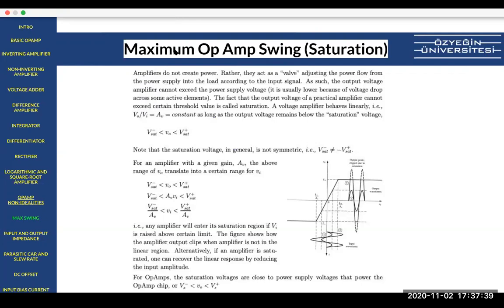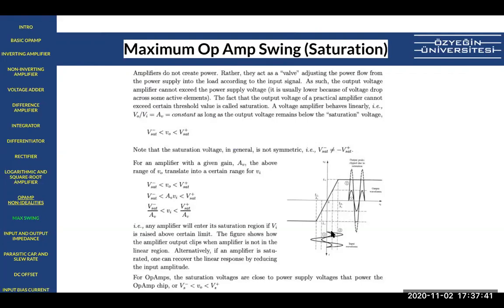You apply an input signal. So this is your input signal here. It's something tiny, right? Just like real life. This is a transfer characteristic. We have a certain region where you can amplify this input signal nicely. Why? Because you don't get into saturation. You don't get into a region where you see these non-idealities.